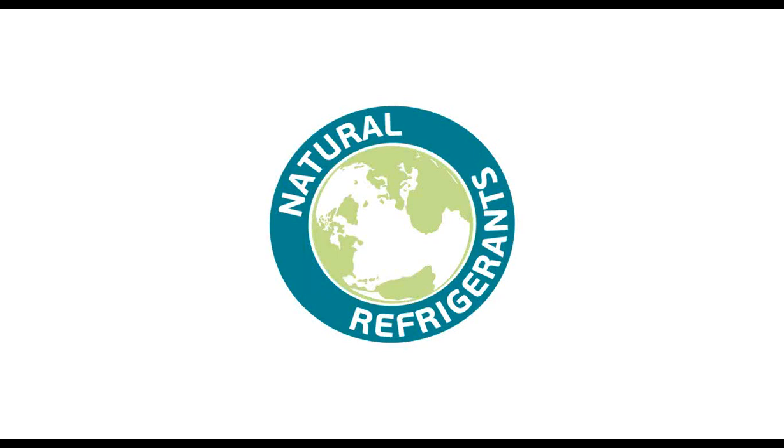Okay, somebody wants clarification on the difference between R600 and R600a. R600a is isobutane. R600, I believe, is just butane itself. R600a is the approved refrigerant. R600 is not going to be a commonly used refrigerant. So I should be clarifying when I say R600a, because yeah, R600 is butane.